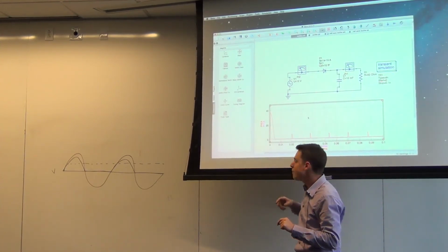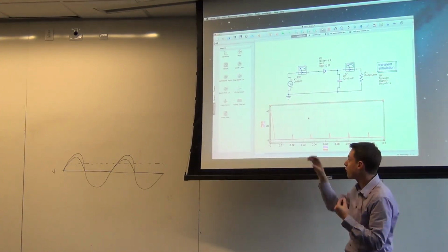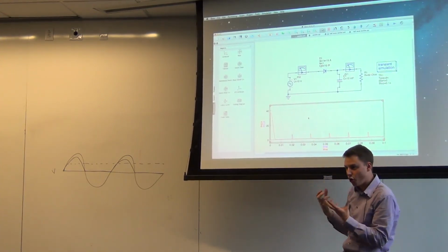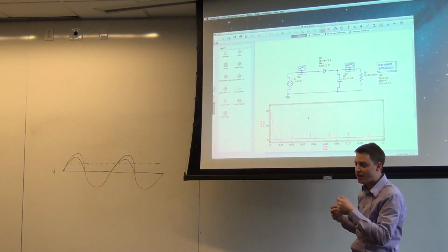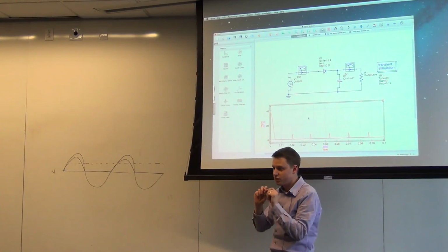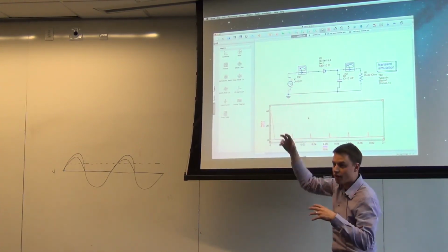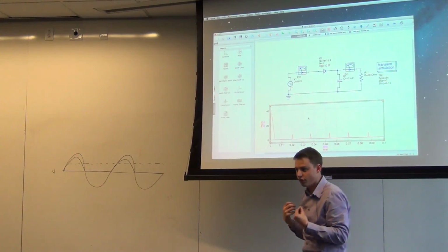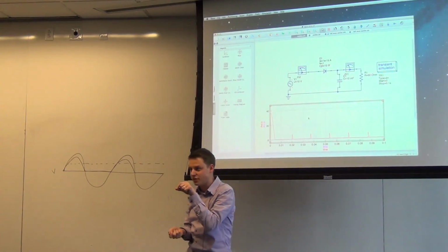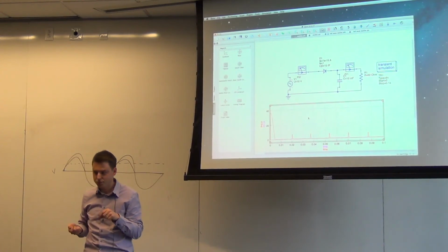And so what ends up happening is that it's only for a few little blips like this that you're actually drawing current from the source. That's providing all the current, all the power of the system, coming from the few little blips in time where you sort of see now my voltage here is higher than the voltage drop here. That will cause a lot of current to come in to charge that capacitor so that it can keep supplying the voltage itself. Does that make sense?